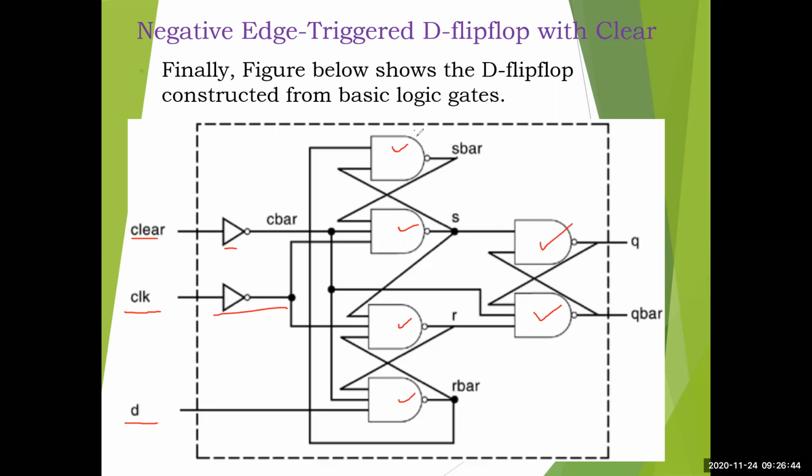Okay, see the first NAND gate. You have S bar as the output on the left side, which is equal to not of AND. Then you have to write the operands, two or three, however many there are. Here it is two operands. You fill these operands from where they are connected in the logic diagram. This is connected to R bar, so this signal came from R bar. That is the first operand, R bar and S. Not of that will be the NAND. So this is the first expression.